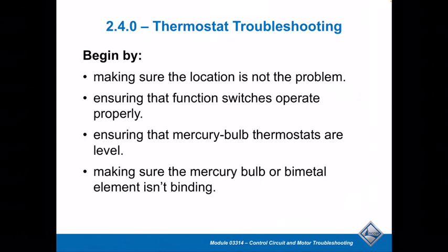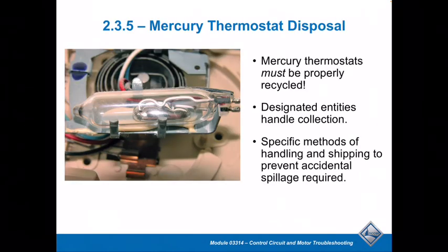Mercury thermostats are thermostats that are extremely level sensitive. So I'm going to go back to this. In other words, the little mercury that's in here is going to swing one way or move the other way. And depending on the bimetal that they're showing here, that wire wound bimetal, that will tilt one way or tilt the other way.